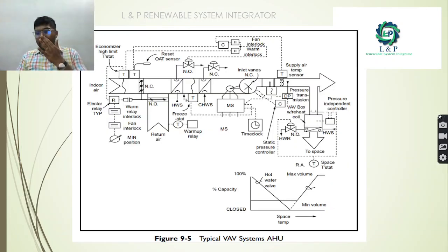As you can see, this is a typical VAV system. Before the invention of these smart devices and smart sensors, previously through pneumatic systems, the entire controlling operation was performed in a particular building, especially for the indoor air intake and the heating operations, and most importantly, in order to perform them at an appropriate time, analog clocks were used. As you can see here, we have a chill water supply, open and closing contacts, and most importantly we have supply fans also.